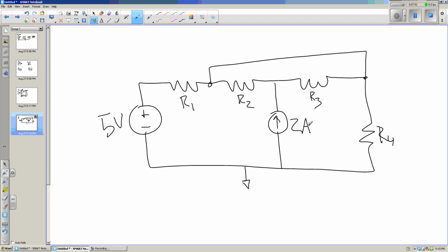And now, where are our nodes? Well, generally nodes are where we expect voltage to be different. So here we've got a node. We'll say this one is V1. We've got a resistor between those 2 points. So we know that some of that voltage is going to get dissipated as heat energy. We have one right here. Again, we have a resistor in between those two.